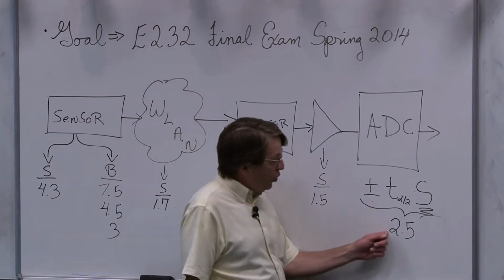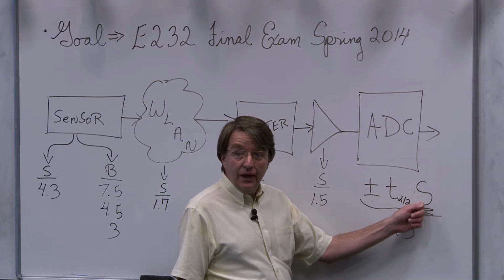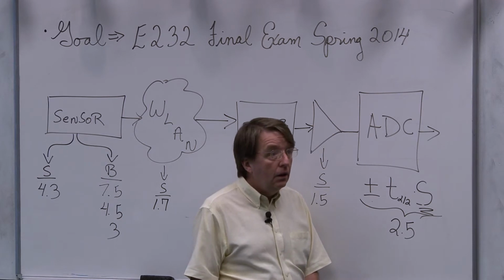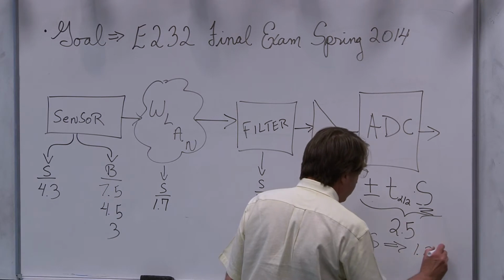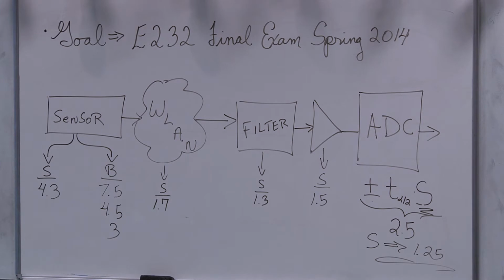So 2.5 equals 2 times S. All right, so what do I get? 2.5 divided by 2 is what, 1.25? All right, so S here equals 1.25. Okay. Now, questions I got during class, it's 2 or 1.96 because of 95% confidence. Are we always going to have 95% on the exam? Yes. So the bottom line is always going to be 2 times S equals the random uncertainty.